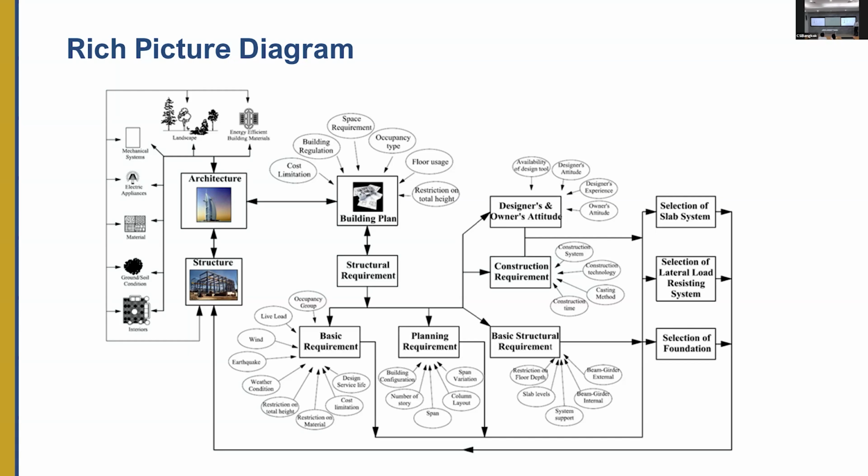I mentioned to you, if you don't know how to design flat slab, it's out, right? And so on. If you don't know how to design post-tensioning, post-tensioning is out, right? Normally most engineers don't know how to design post-tensioning, so they give it to the contractor. So the contractors who do post-tensioning also do the design. And this creates a serious problem because now suddenly floor design responsibility is divided between two people.